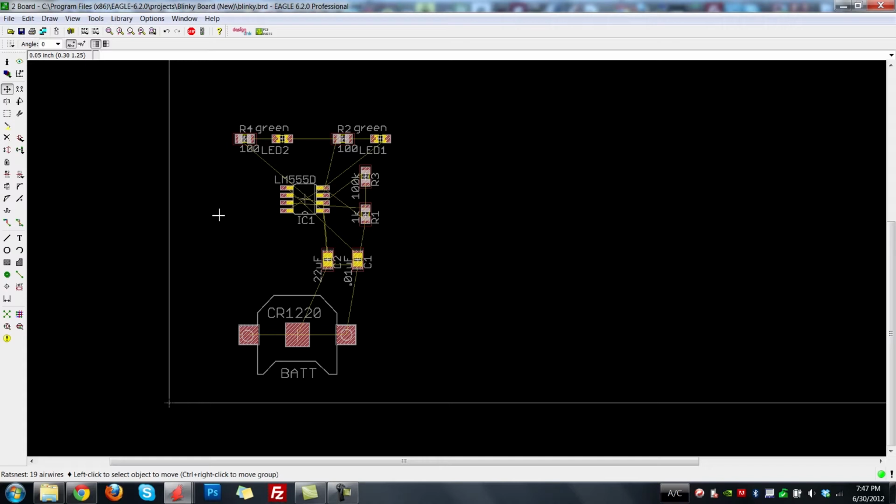There are a few ways that you can go about actually making the connections between these things, which I'll talk about now. You can use Eagle's auto router, or you can do all the routing manually. You can also add things like ground pours and define net classes that determine certain thicknesses of certain wires, how far apart they have to be from each other, and things like that.